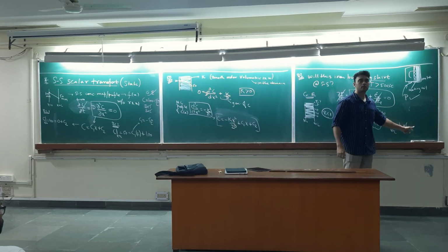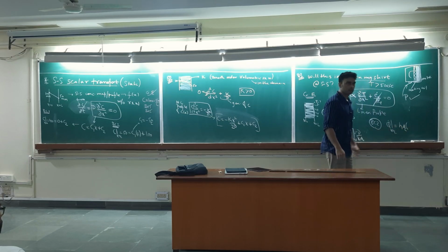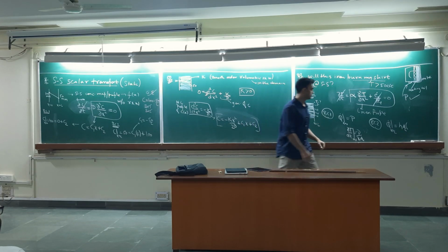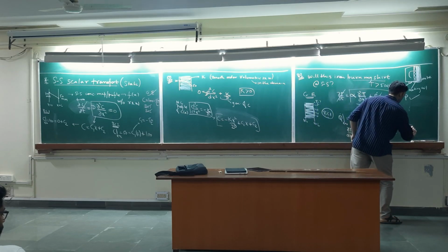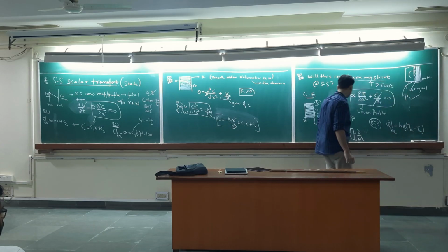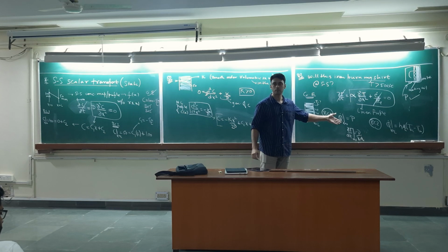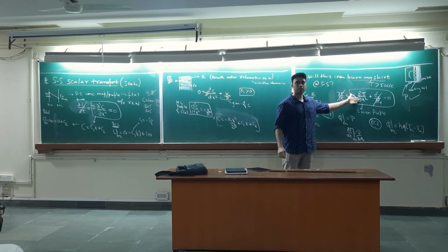What should it be? T at lower coordinate minus T at higher coordinate. Why am I saying all this? Because if I have flipped it, it might cause some confusion. So T_L minus T infinity, that is, T at x equals L minus T infinity. Okay, now it's very easy to solve. It will be a linear profile, same C1 x plus C2.